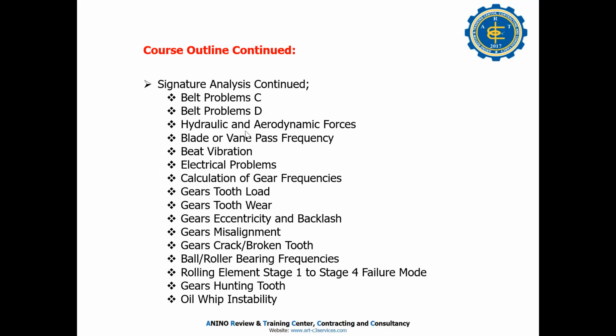Many times I encounter this hydraulic and aerodynamic forces in the field during collecting data. Normally if you hear abnormal sounds from the pumps, then if you collect the data, you can see the signature for the aerodynamic forces and also the blade pass frequency.